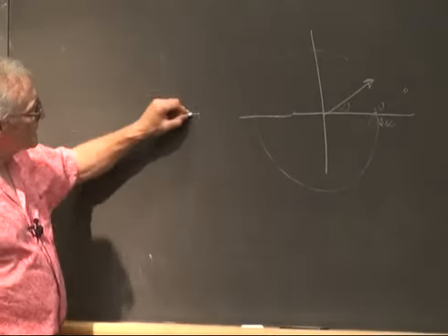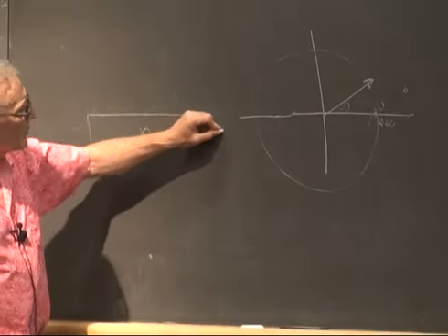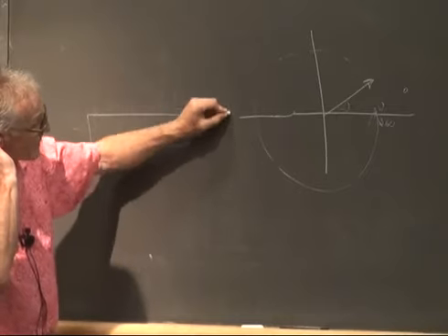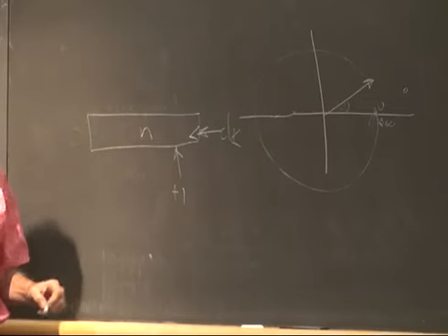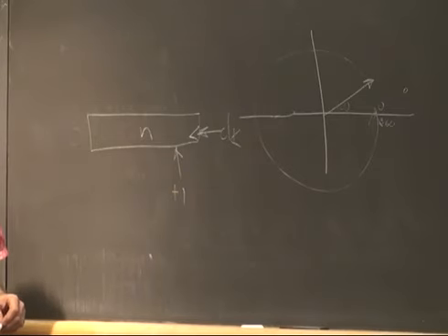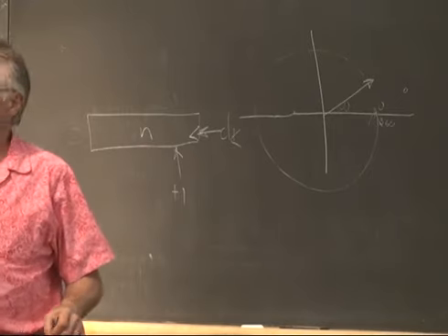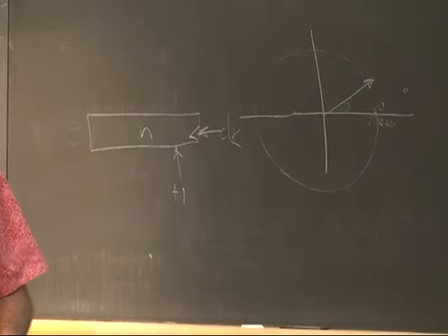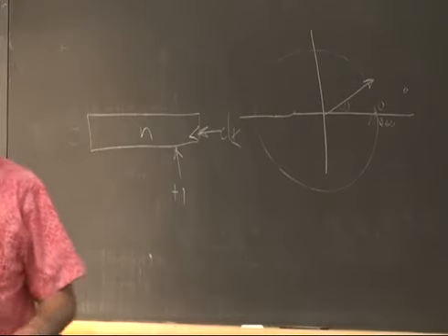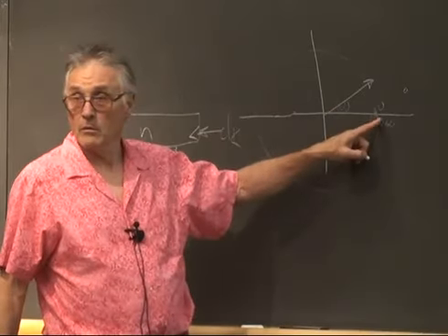That is exactly the same topology as having an n-bit register that you increment on the clock until it overflows back to 0. So we're going to define a scheme for generating a sine wave based on 1 cycle per register overflow, which will be directly related to 1 cycle per phasor overflow back to 0.